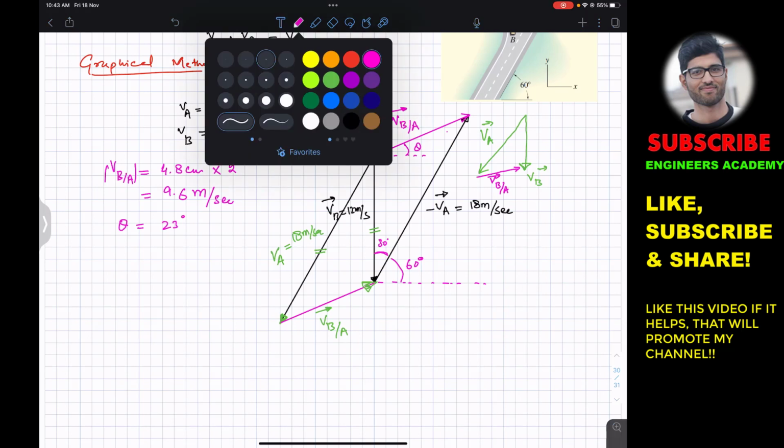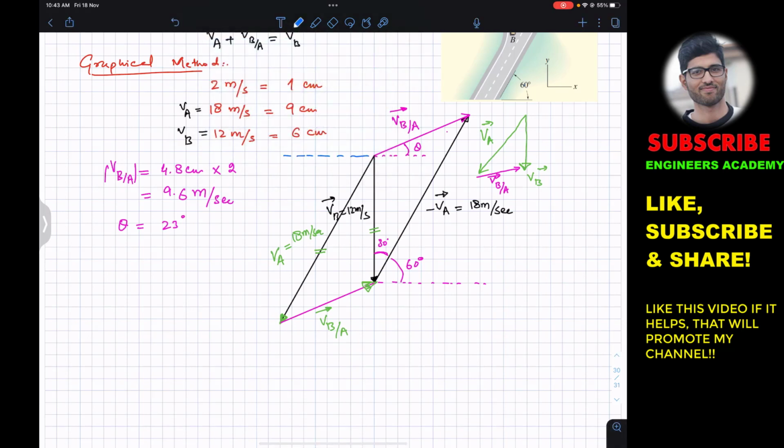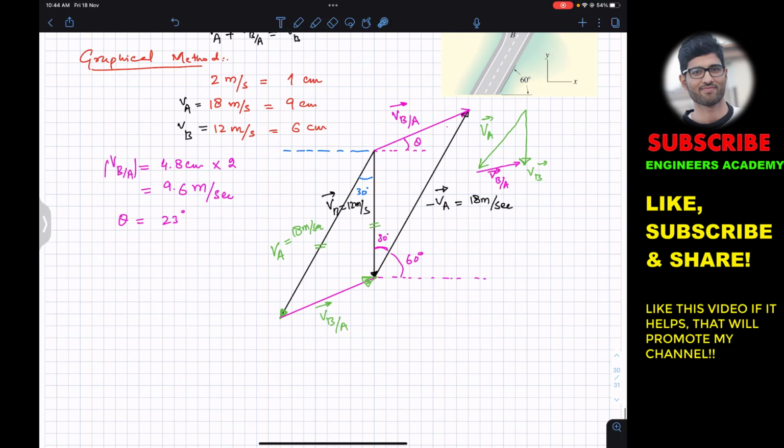Similarly, if I draw a horizontal line here, again this VA vector is making 60 degrees. This is vertical, this is 90. So 90 minus 60, this is 30. So this angle is also 30. And if we look into this diagram, this line and this line are parallel to each other, so this angle and this angle are alternate angles. So this must be equal, 30 and 30. So now we know the angle between this vector and this vector, so we can find this magnitude by using the cosines law.